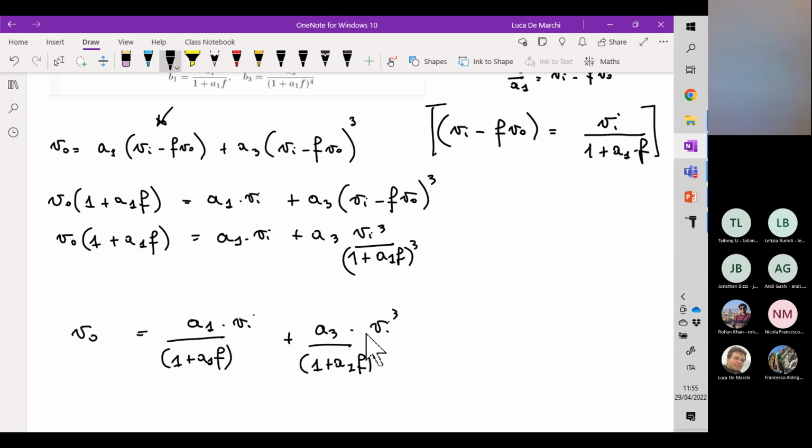If f is mandatorily smaller or equal to 1, then 1/f has the smallest value when f is equal to 1. So if f is equal to 1, we have the most difficult case to compensate, because f equal to 1 means substantially having a curve at this point, where A null is equal to 0 dB.